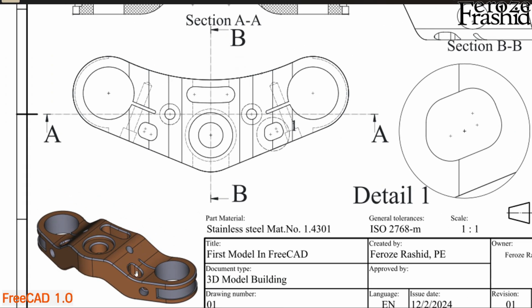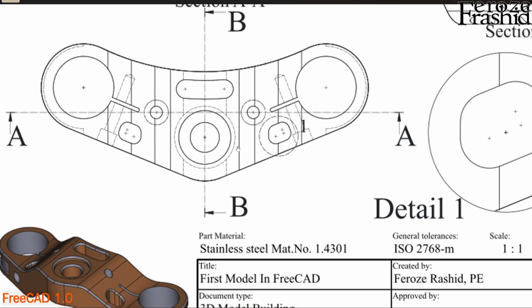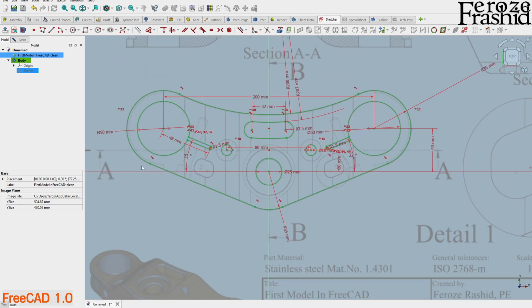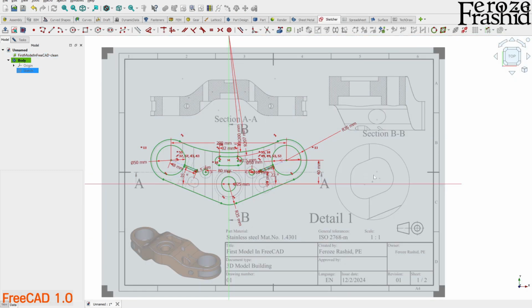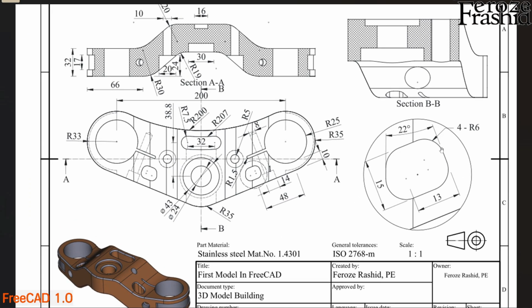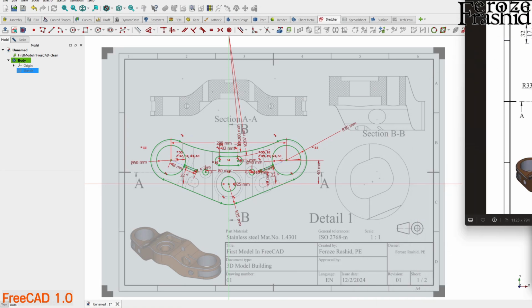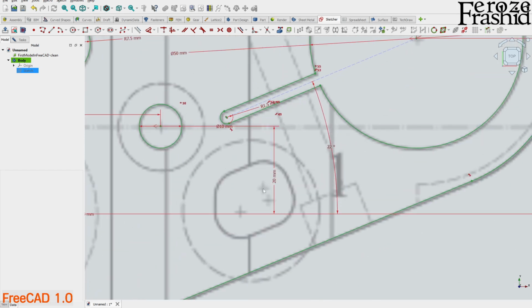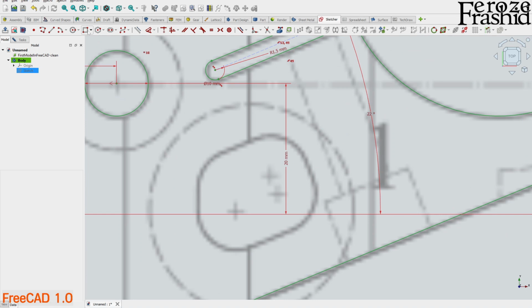Those holes are going all the way through, but it's not fully rectangular. There are some detailed instructions to it, so let's draw that. It comes in the inset. I have that in here. We'll have to draw this rounded rectangle, but it's not a rectangle. It's actually a trapezoid, a rounded trapezoid. So let's draw that. I want to start off with a rounded rectangle, something like this, and on the radius, I think it's 6 millimeter radius. So we got that.